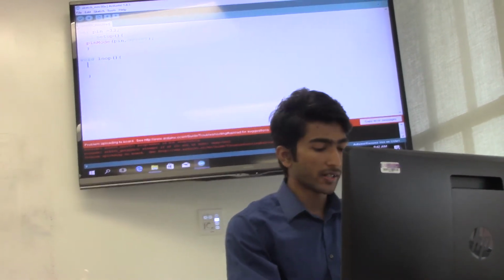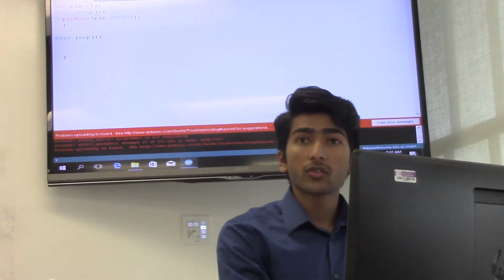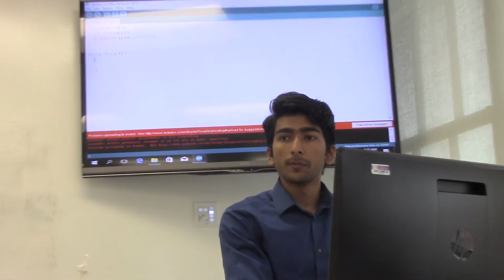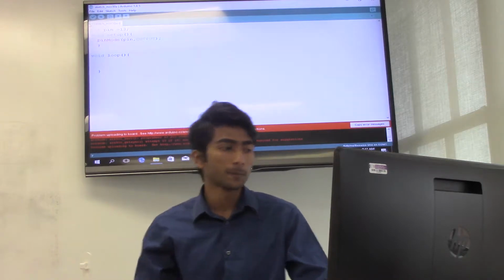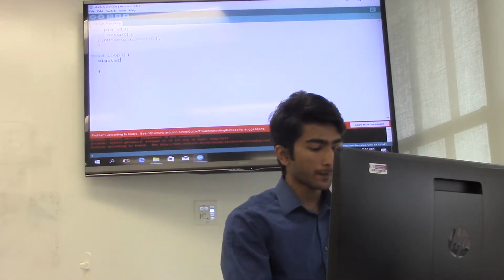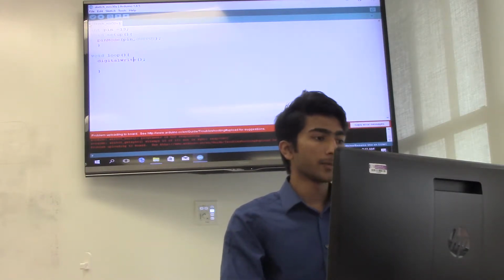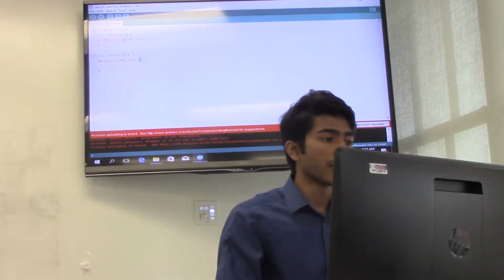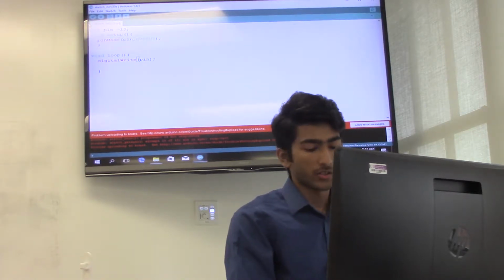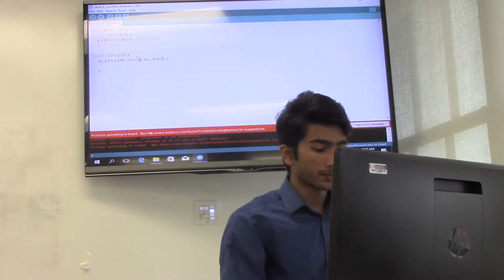So what I'm going to do here is use a function called digital write. Digital write sends a signal to a given pin, and there are two signals that you can send: a high signal or a low signal. So let's see what happens here. The function name is digital write, and notice that here W is capital. And then the first argument that I'm going to pass to this function is the pin variable, which is pin number 13. And then I'm going to set this to high.